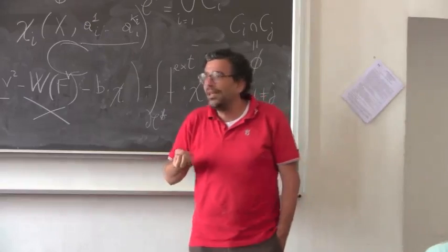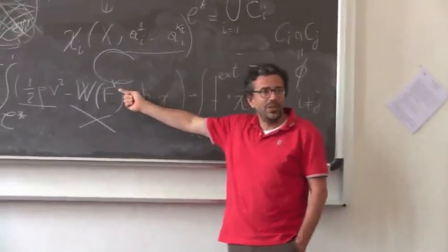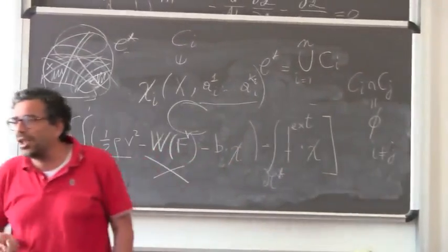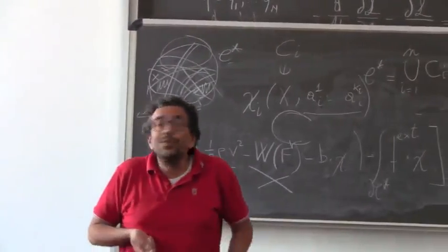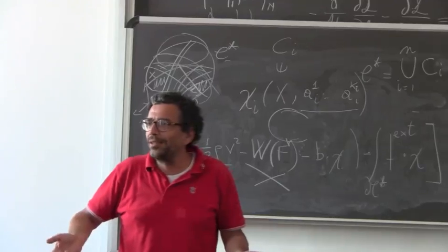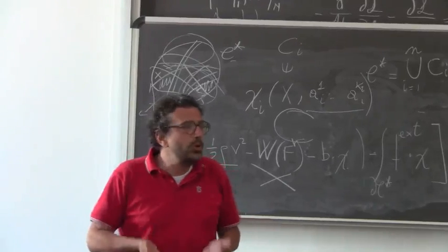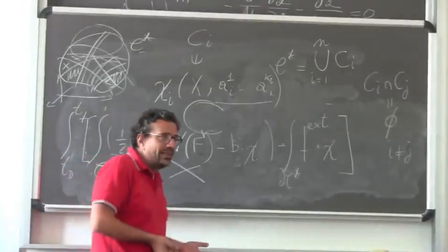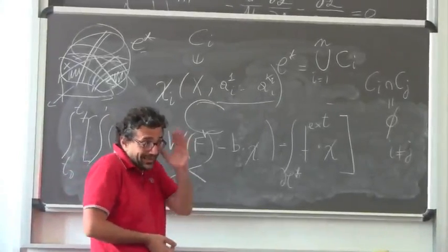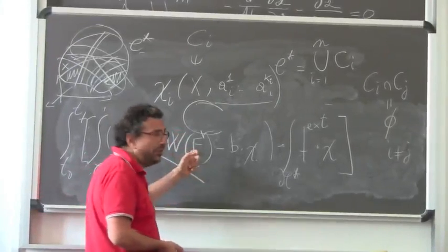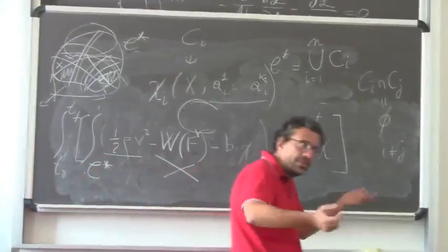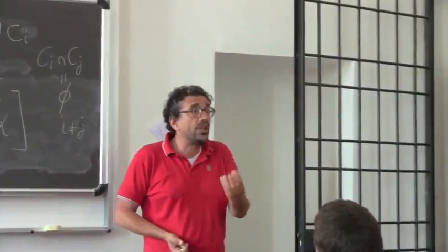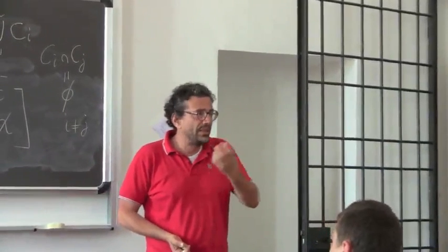You become blind if you consider a first order polynomial approximation and you have an energy of second gradient. You don't see the second gradient, see? Because your polynomials are too simple. So a wise man will consider at least second order polynomials if he wants to study second gradient materials. Okay? So what I'm telling you now is very important for choosing the correct finite element in a given problem.